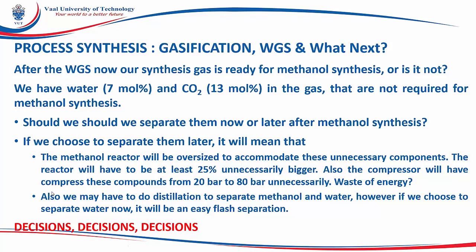Okay, after the water gas shift, now our synthesis gas is ready for methanol synthesis, or is it not? If you look at our stream, we have 7 mole percent of water, and we have 13 mole percent of carbon dioxide. These two components are not required for the methanol synthesis. So we need to start thinking about what we are going to do. Should we separate this? Should we remove water and carbon dioxide before methanol synthesis?